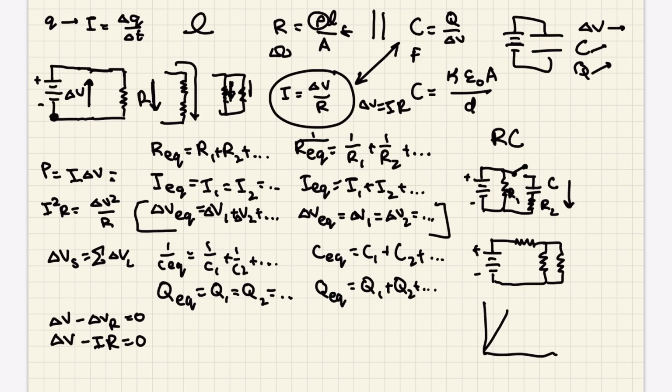Well, you start going up, that's the battery. We're starting at this point going up. Then you go through this resistor, but before that there's some wires, so just some flat space. Then you go through this resistor, which brings it down, but not all the way down, because at this point you're not going to have zero voltage. That's not a complete loop. This is a complete loop. This is a complete loop, but that is not. And so it's not going to be zero voltage at that point.